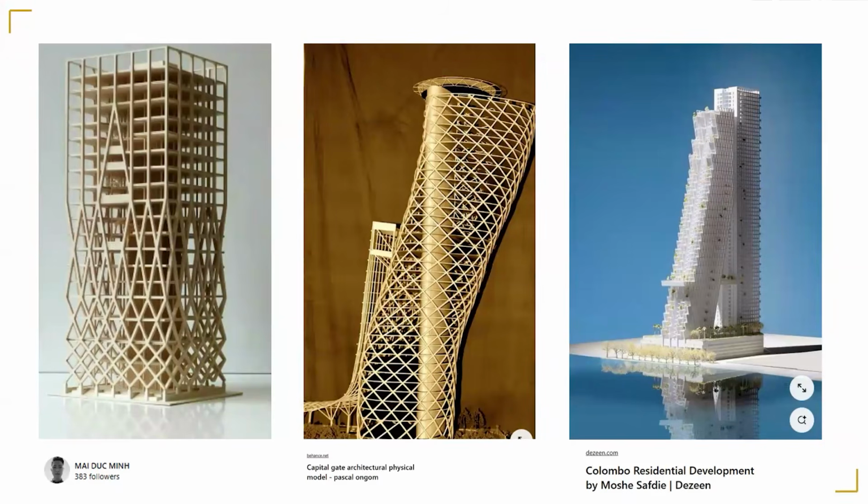Look at this building on the left-hand side. This is a perfect example of optimization called generative design. So they let the system find the best form. How many diagrids I need, not just put the diagrids everywhere, how many columns I need. So they start with a micro mesh that you see, they put grids everywhere first, and they run the system one by one. Every element that doesn't carry any force, remove it, until they're left with the minimum elements, minimum verticals, minimum diagonals, minimum beams. So everything that is not participating is removed from the analysis in the next cycle.